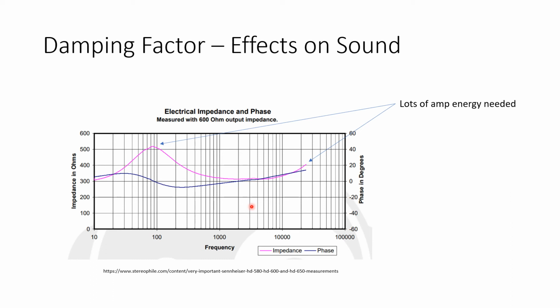All right, and that's important because, again, it is a zero-sum game here at any given instant in time between the energy the output impedance takes out and transfers to thermal energy versus the energy available for the driver to convert to mechanical energy. And then we also have a variable damping factor here. High damping factor here and here because the load impedance is high.